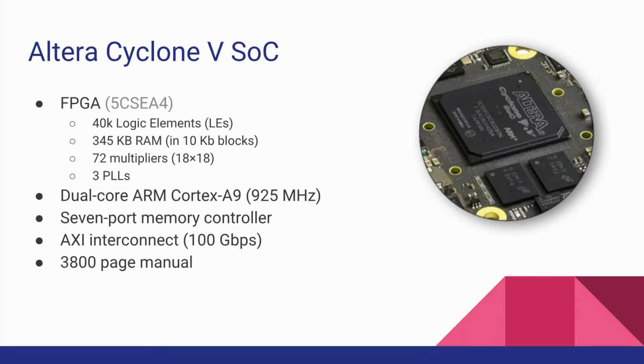And it's got phase lock loops if you want to change the clock. These boards typically come with a 50 megahertz clock, but internally you can bump that up to anything you want with a phase lock loop. If you want to run at 100 or 200 megahertz, you can. Or if you want to put out a video source at a specific frequency, like 15 kilohertz, megahertz, whatever, you can do that. The dual core ARM running at a gigahertz didn't hurt either. That was awesome.